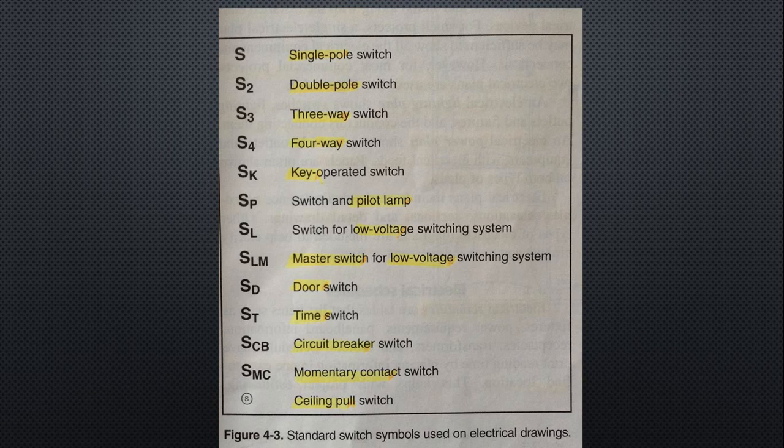The number of conductors in a conduit run is shown by small marks across the conduit line or the conduit run line. Hot wires are shown as full marks. Often neutral wires are shown as half marks, which may be centered on the line or entirely to one side. See figure 4-1 in the text to see this.